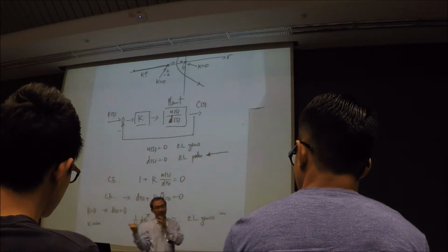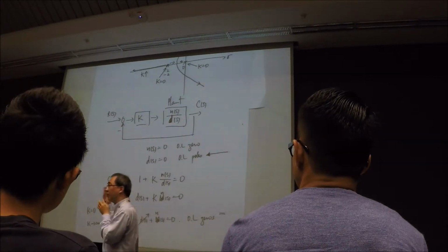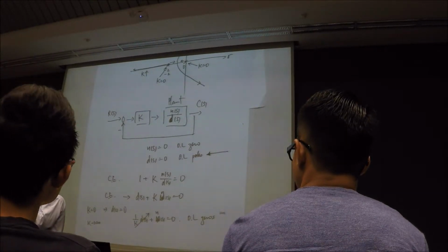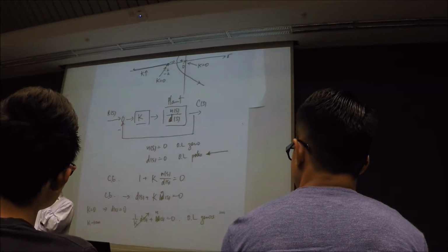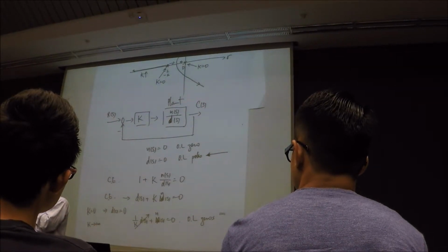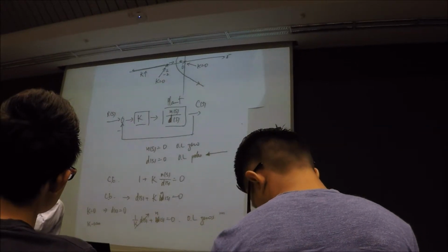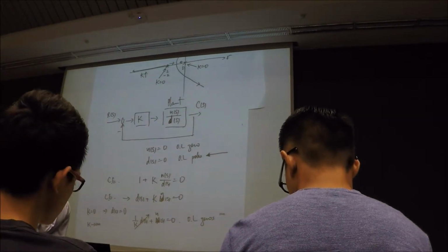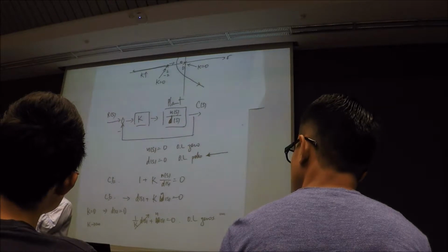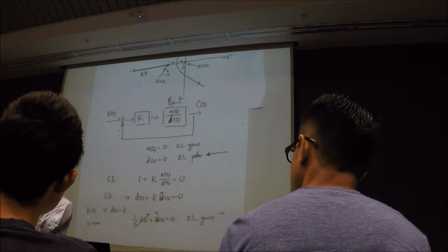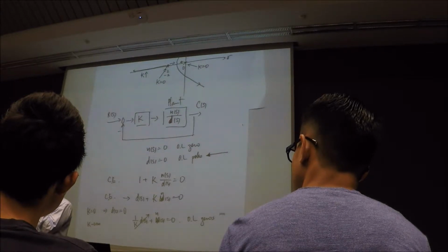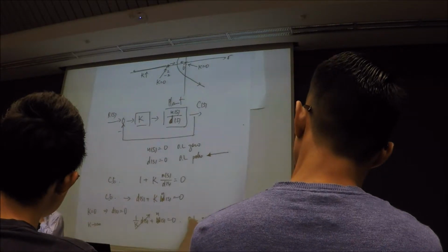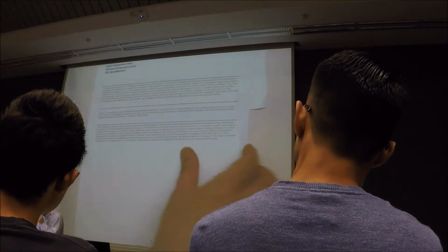Next question. If I look at my transfer function and I have 3 poles and no zeros, then how can it go from open loop poles to open loop zeros? Think about it. If you still can recall from the very second lecture we discussed this, you have your finite zeros, and you also have your infinite zeros. We mentioned before, if you have a transfer function, you can work out what are your finite zeros and what are your infinite zeros.